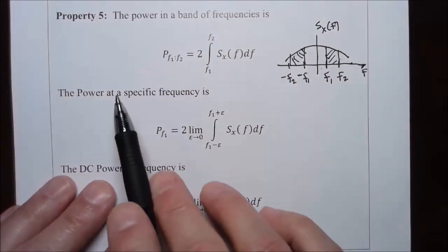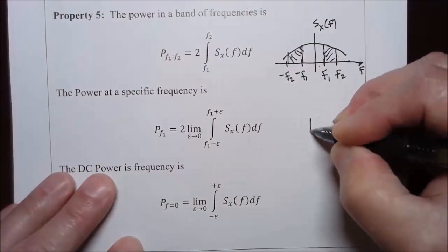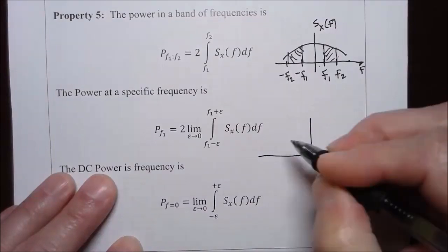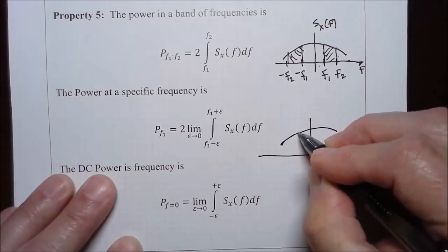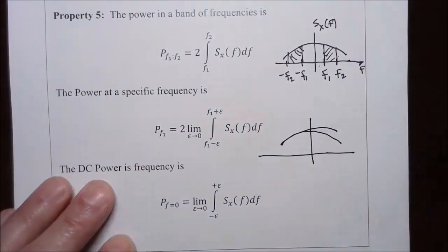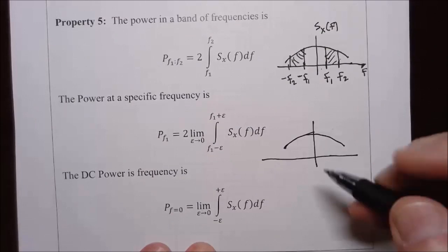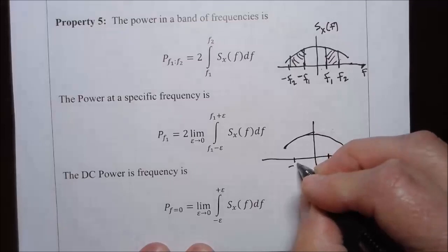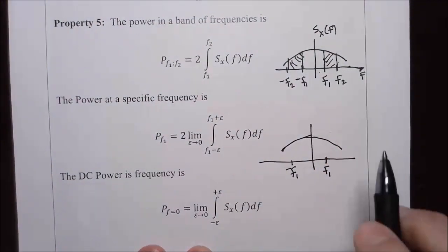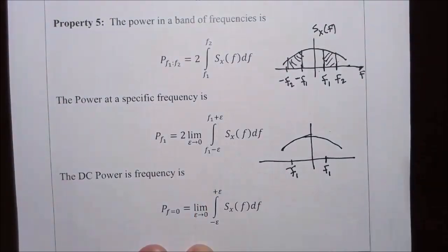Now, if you want to know the power at a specific frequency, then what you can do is... I should have made this more symmetrical, I suppose. Here, you can watch me use the magic wand. If we want to know the power at a specific frequency F1, then we're going to integrate. When you integrate, you have to integrate over a range of frequencies.